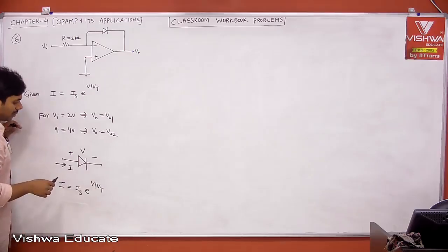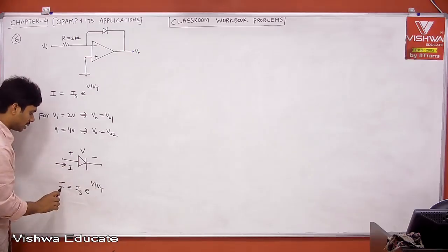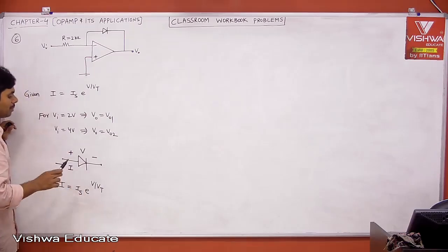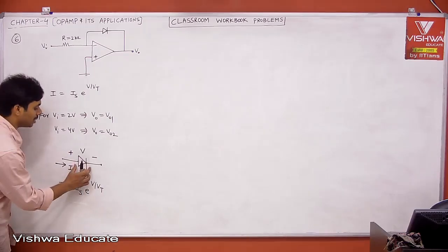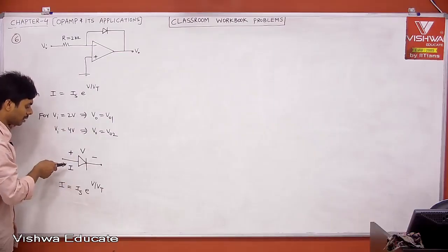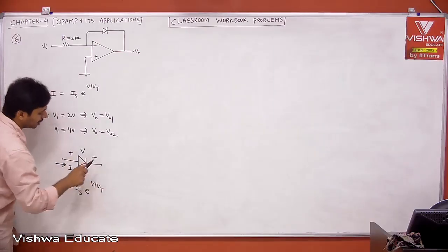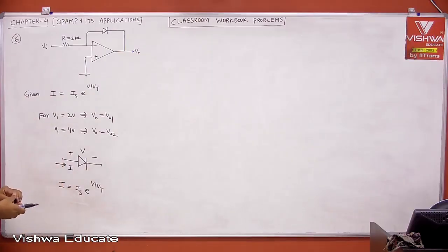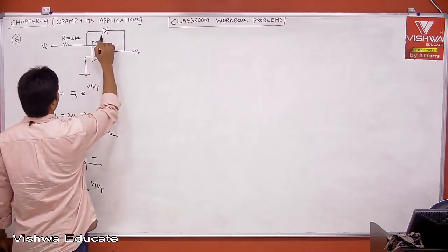But if you take the typical equation, I is equal to I0 into e to the power of V by eta Vt minus 1. But remember, V is nothing but the voltage across the PN junction diode treated as forward bias voltage, and the current I is the current flowing through the PN junction diode, which is from P to N. Okay, this is the direction. That is what is given here also, where V is the voltage.